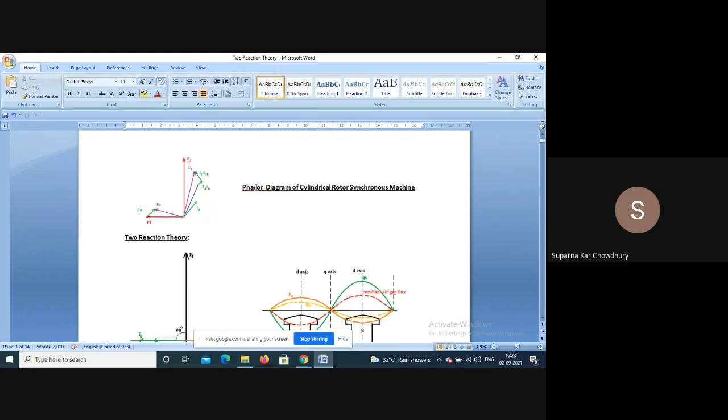That is, we take the voltage as the reference with current at a phase difference theta degrees away from terminal voltage. Then we can add the drop related to resistance and synchronous reactance, and we will get Ef. So it is possible to draw the phasor diagram from the measured data, and from there approximate regulation also can be calculated, though that is not very accurate.